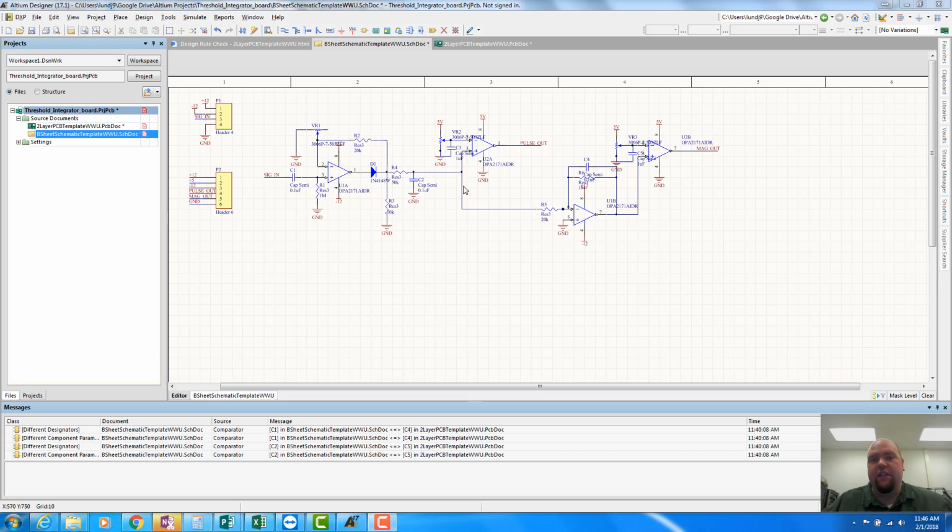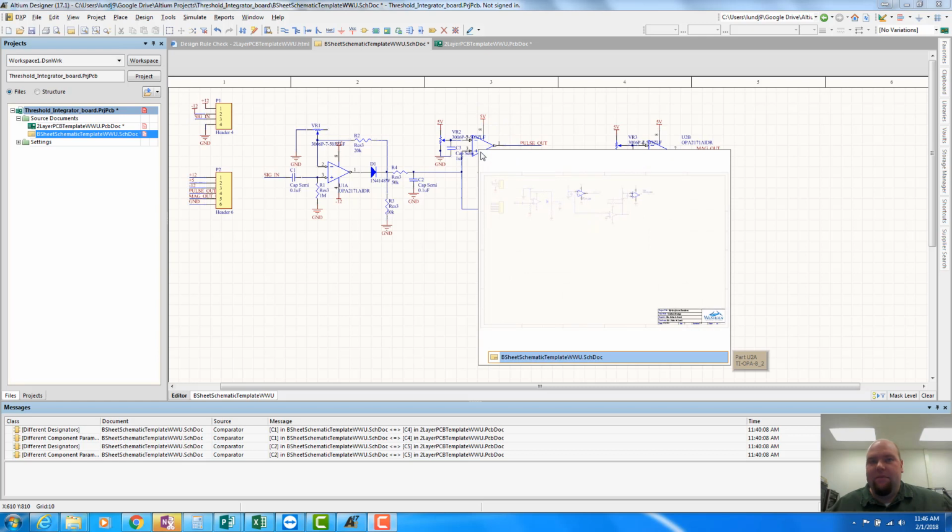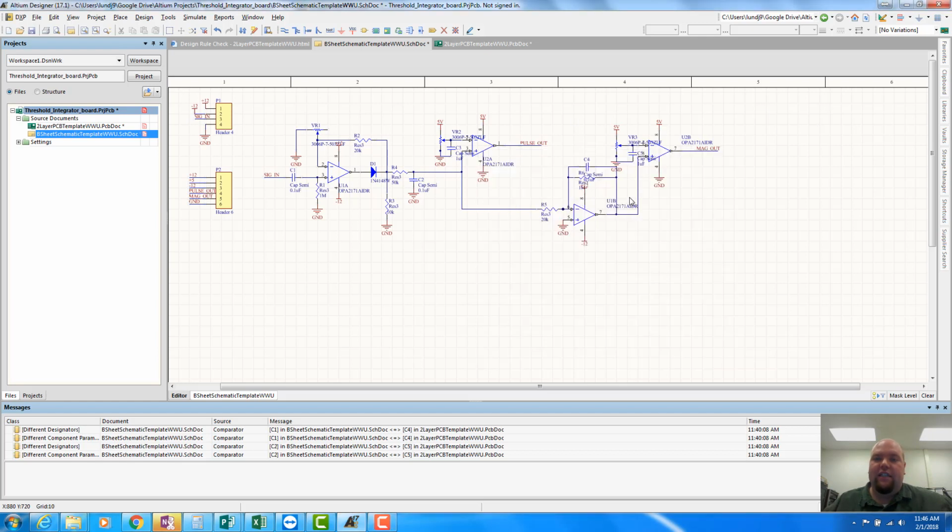is going to be. So essentially we have one signal coming out of this, which is a pulse which says, at this immediate moment in time, does the signal I'm getting from this hydrophone exceed my threshold? The second one says, not only does it exceed my threshold, but based on how large the amplitude of that signal is, we're going to get a longer pulse coming from this second signal. So it's kind of a two-part system that looks at the immediate value of the sample and also the magnitude of the sample.